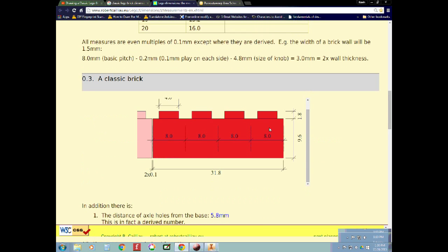And somewhere, so right here, that we have the distance here to here to here. Those are 8 millimeters. So we're going to go from center to center, from the center of the one we just drew, 8 millimeters to the left and 8 millimeters to the right, and that'll give us our other